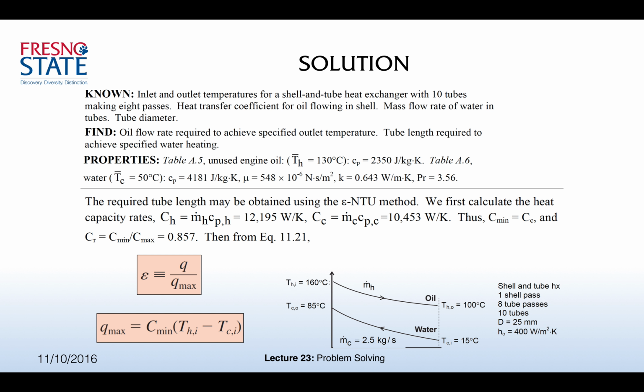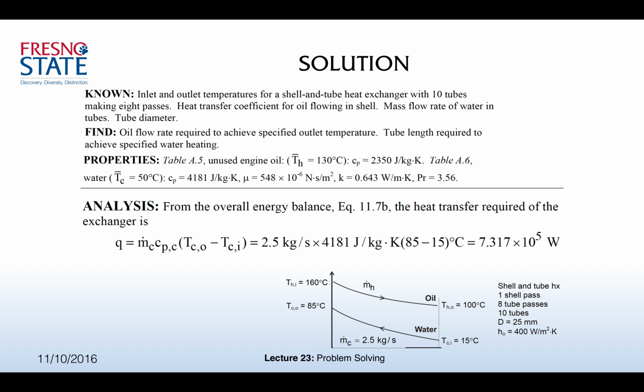And my m dot h in this case, if we go back to this expression, is going to be Q divided by Cp hot divided by the temperature difference for the hot oil.